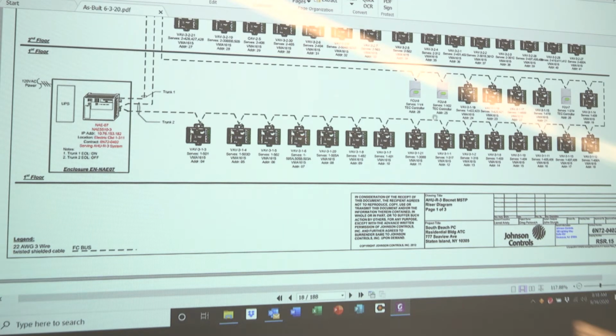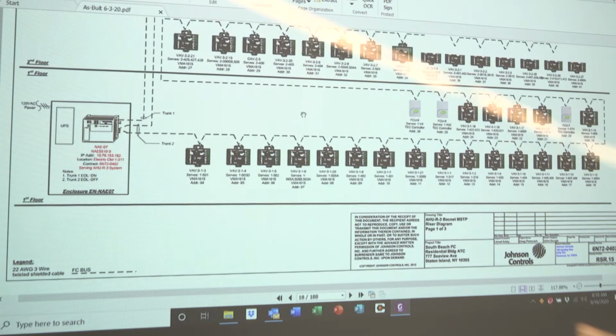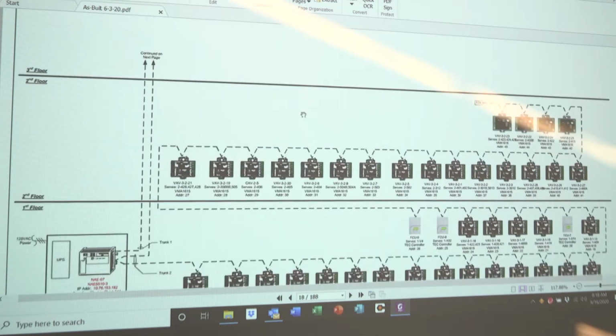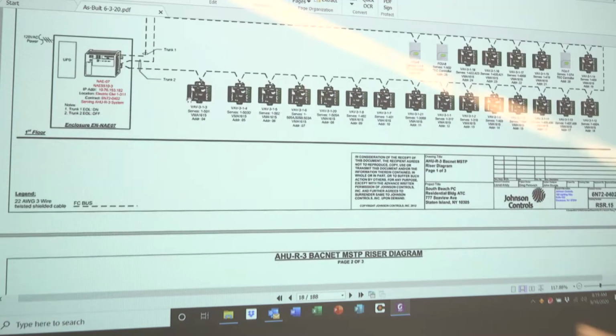Okay, these fan coil units are all located at exterior entrances. There's a couple different style fan coil units. Most of them are an exposed cabinet, just a unit hanging in the ceiling with a hot water coil. Okay, they're designated as fan coil units. They are heating only. The communication link picks up these fan coil units, continues up the floors. Okay, you see the separate trunk going up through to the higher floors.